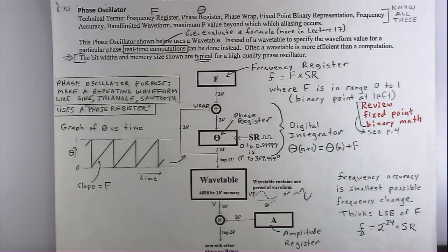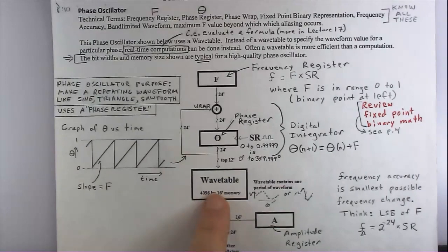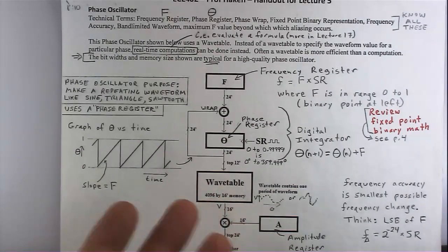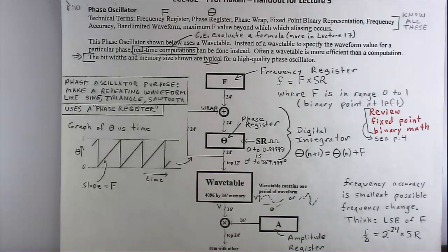So that's what that wavetable is doing for you. But you're not reading every sample in here, and that's often a confusion. You could just think of this as implemented as a table lookup, but it's basically just a function, right? It's really quantized, but it's just a function. You can think of it as just going into any other function, and that's just the phase going into it.